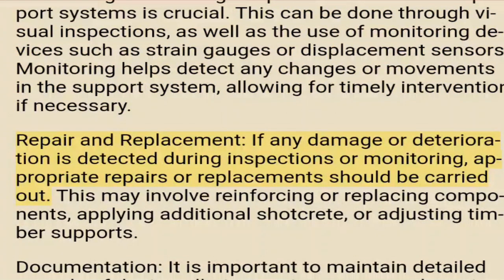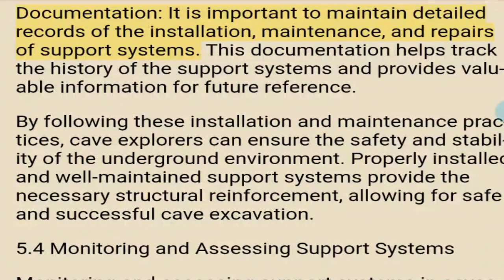Repair and replacement. If any damage or deterioration is detected during inspections or monitoring, appropriate repairs or replacements should be carried out. This may involve reinforcing or replacing components, applying additional shotcrete, or adjusting timber supports. Documentation. It is important to maintain detailed records of the installation, maintenance, and repairs of support systems. This documentation helps track the history of the support systems and provides valuable information for future reference.